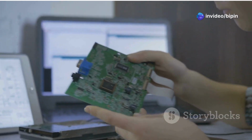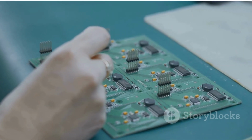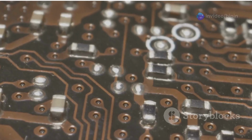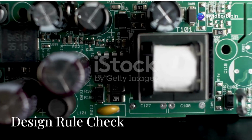Use your schematic as a guide to ensure that you are connecting the components correctly. The width and spacing of your traces are important for ensuring that your circuit functions correctly. Thicker traces can carry more current, and proper spacing prevents short circuits.